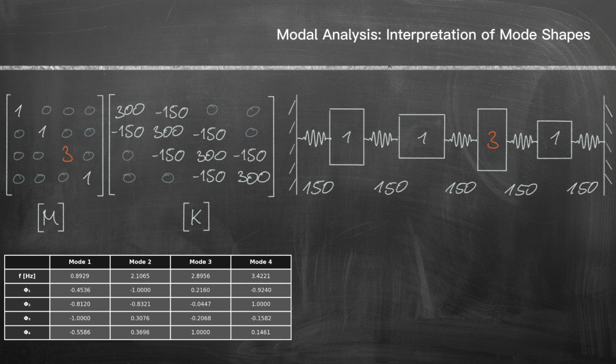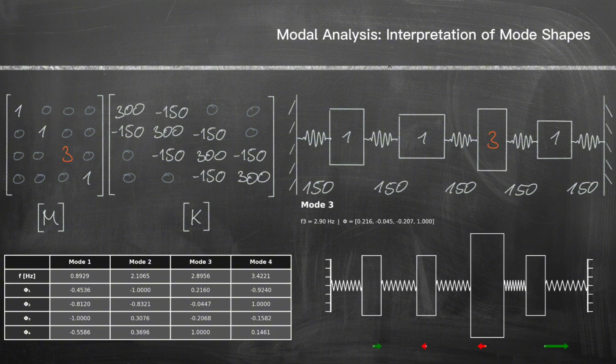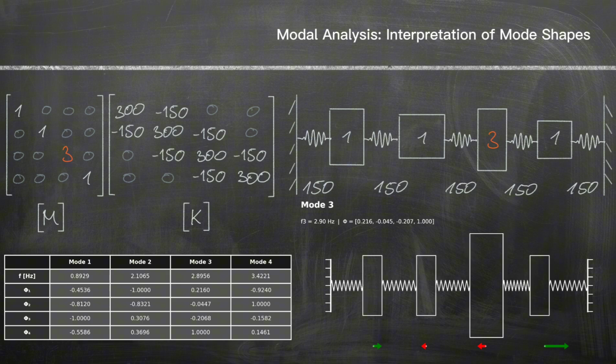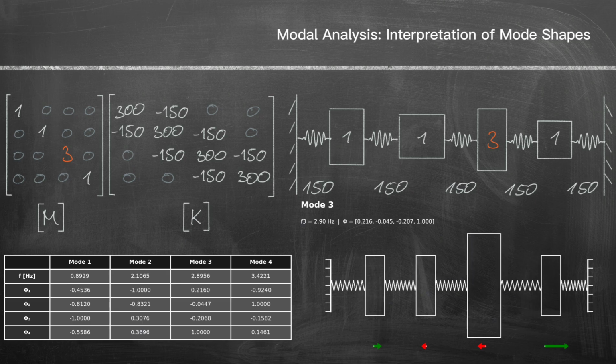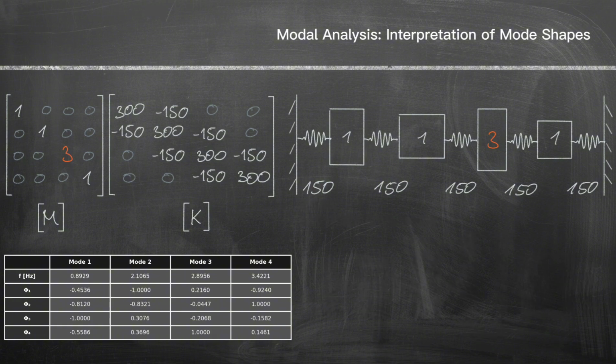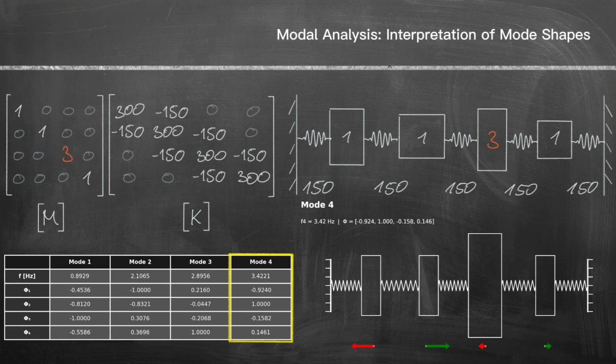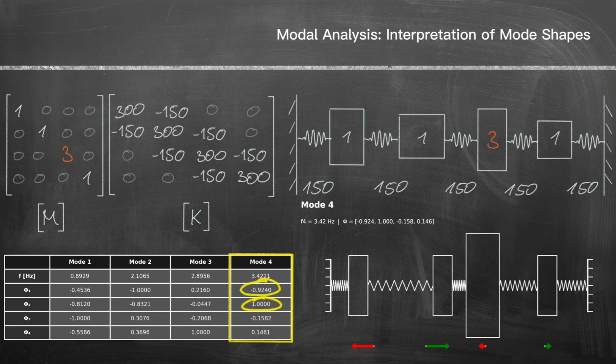From the eigenvalue problem, a larger diagonal entry in M means that for a given stiffness, acceleration at this degree of freedom becomes more, let's say, expensive in terms of frequency. As a result, eigenfrequencies decrease and mode shapes for higher frequencies adapt by concentrating motion where inertia is lower.